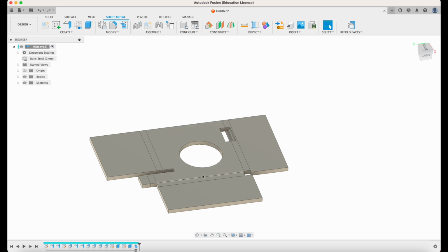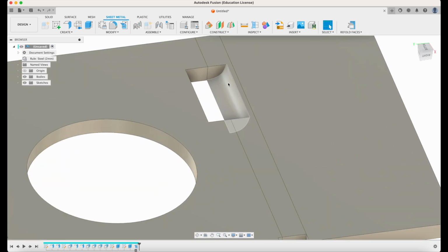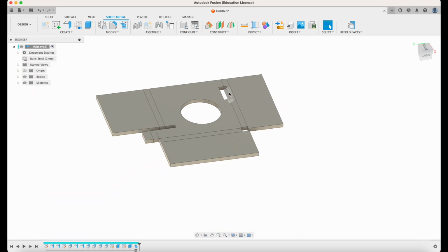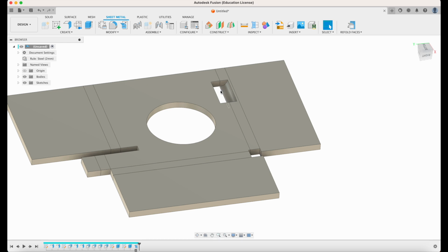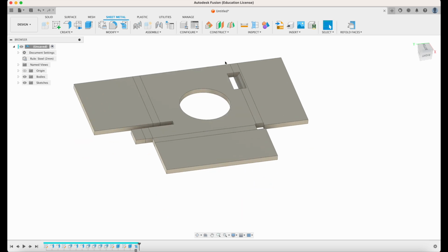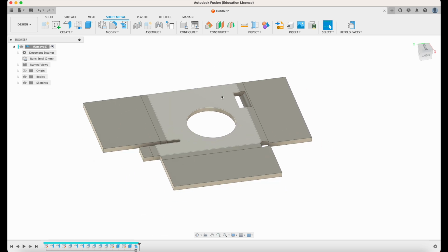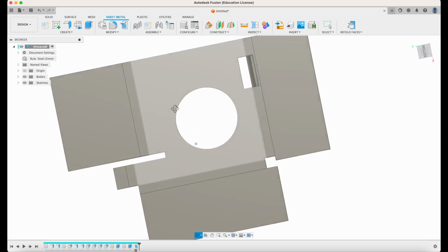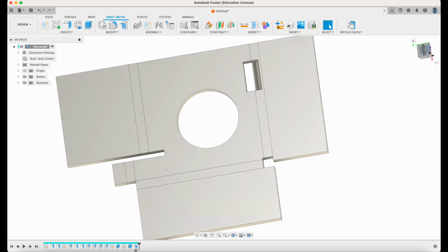So when you input this form into the machine, it will give an error because of this part. It will not be able to process this. So that's why you have to pass the bend when you're doing a feature like this. Okay? So that's important. Now, let's do something while we open this up.